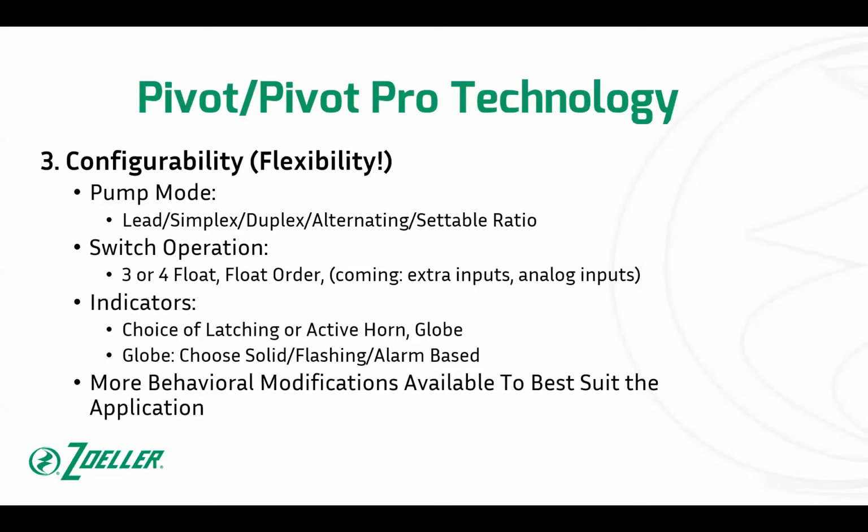If somebody's asking about tanks that aren't necessarily set up for pump down, was the question related to pump down, or what was the other? It's more that you're using a stormwater retention tank, and you're only allowed to send a certain amount of water to the city, in GPM or gallons per hour, or maybe if you're using it for rainwater harvesting, you may want to keep a certain amount of water inside the tank. And that would just be where your extra float is for a stop, probably.